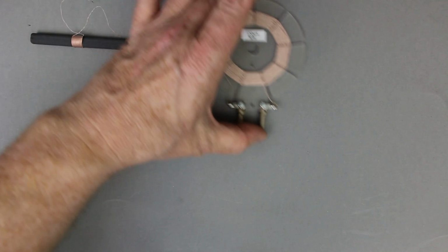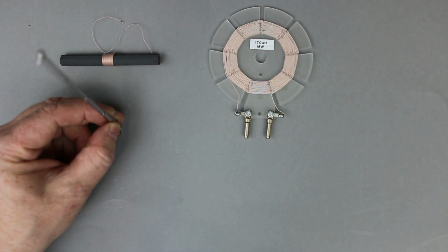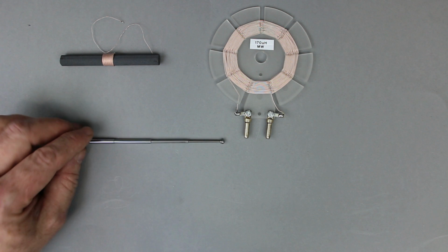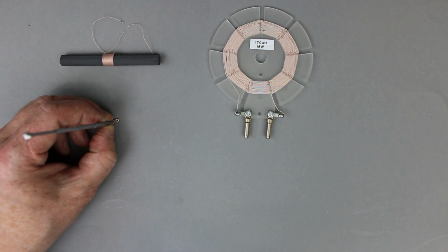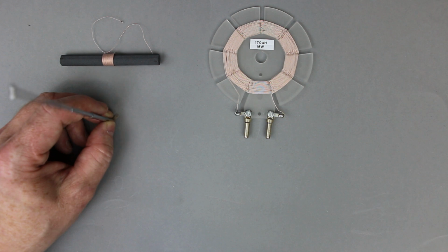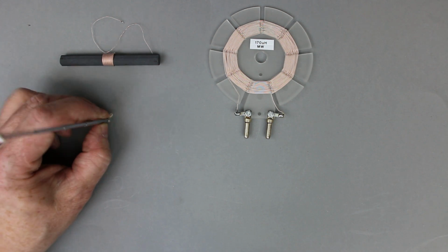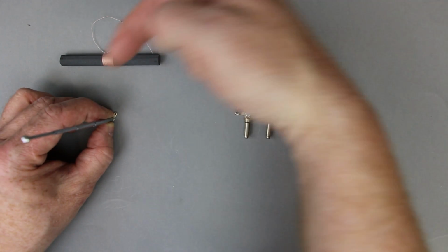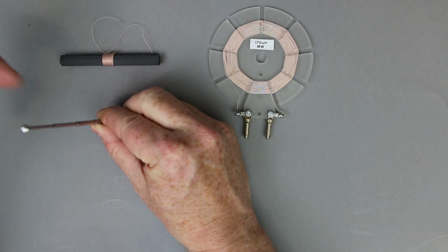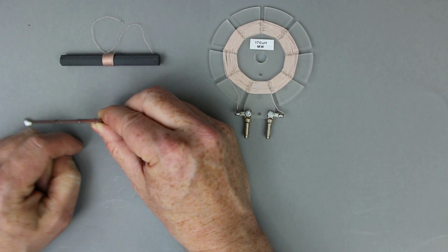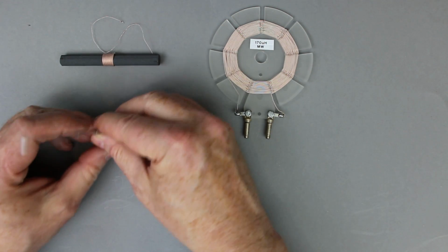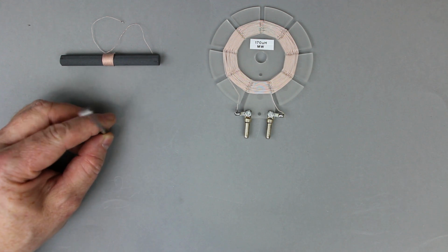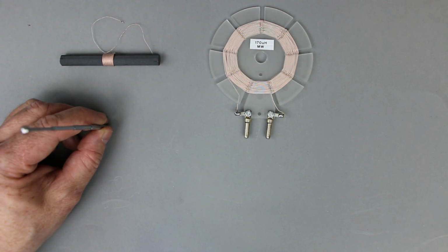There's another reason why magnetic loop antennas are better for AM reception than these electrical rod antennas. Rod antennas have no directional sensitivity, which means when you put them upright, they will receive any transmitter signal from whatever direction it comes in with the same signal strength. So you cannot blank out any station. Well, perhaps a little bit, but the effect is not very great.